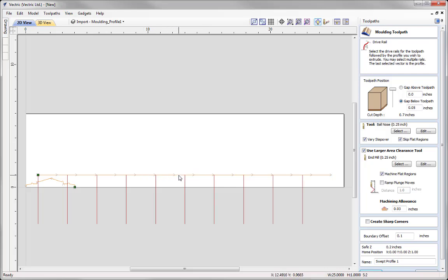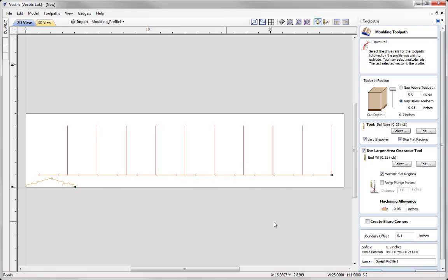To do that, right mouse click on that rail, and you'll see we're presented with the option to reverse the direction. If I click on that, it will now position that above the rail so it looks correct. You can also look at reversing the direction of the cross section to change where the end is positioned or being hung along the rail.